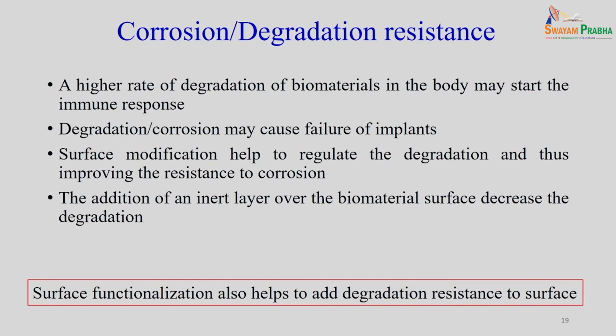So, because of this mismatch, we have to regulate its degradation or corrosion behavior. Apart from that, there are other materials which get corroded, particularly in the biological environment. So, this higher rate of degradation may start the immune response. Finally, it may lead to the failure of the implant.